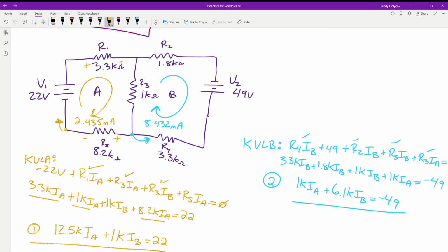And now remember, when we measure this, we're going to be measuring from left to right, top to bottom. So when we'd be measuring it, we'd be measuring positive probe here, negative probe here, positive, negative. We've got the most negative, so we're going to put the black of our probe here. So these values are going to be positive because this is going to be closer to the negative pole. This guy, what about R2? What's the polarity of it? Positive, negative from left to right, because of this current flow, we're assuming conventional current flow. This guy, positive to negative going that way.